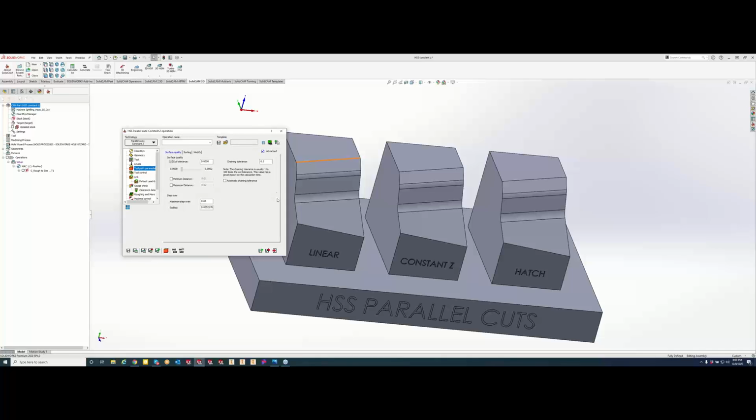Toolpath parameters. Now, in here is basically, think of it as how nice of a finish are we looking for. Now, how I do HSS and 5-axis, and for those that have been in the night class for a while, HSS and 5-axis are the exact same operation. The only difference is the tool axis control that is added in here in 5-axis. So think of this as a building block. So we got our geometry, we got our tool. At that point, I like to do a save and calculate. I like to see what kind of tool path I'm putting on there.